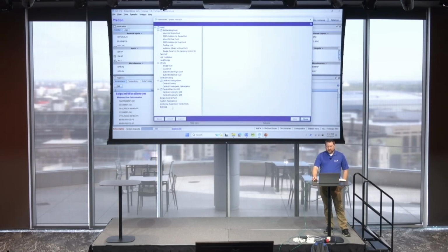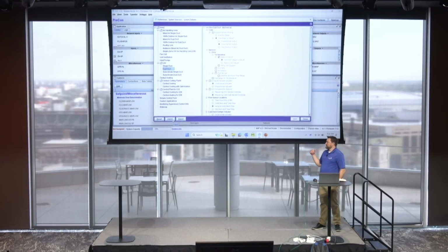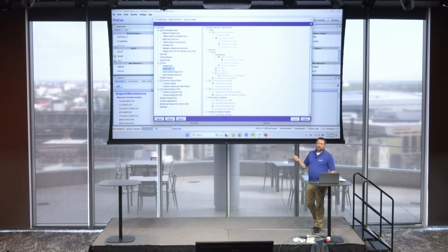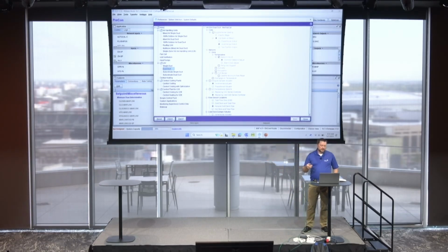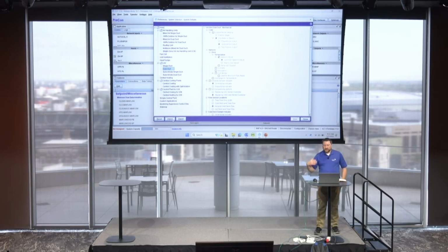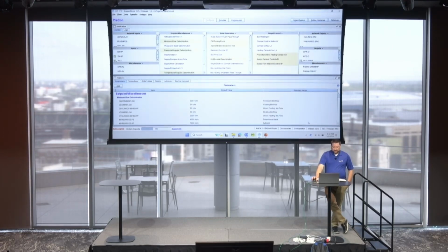Another thing you'll notice is once we did that, you can import and export different default settings. So if you've got a new tech coming on, and you're a senior tech, you've got this developed based on the engineers you've been working with for years, you can just export that and import those defaults to anyone else. So your newer techs don't have to sit there and set their defaults each time. That's just one of the tricks that I like to use in CCT.